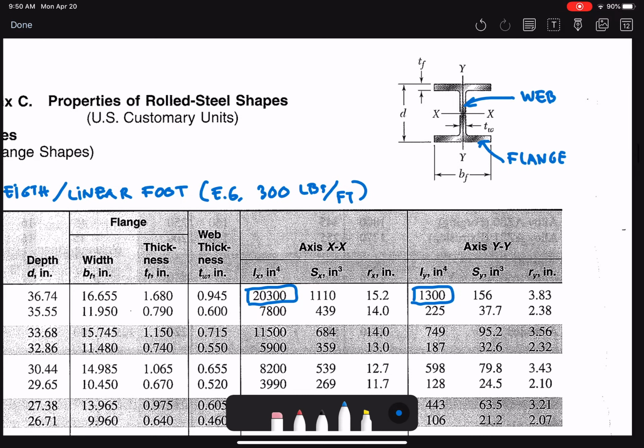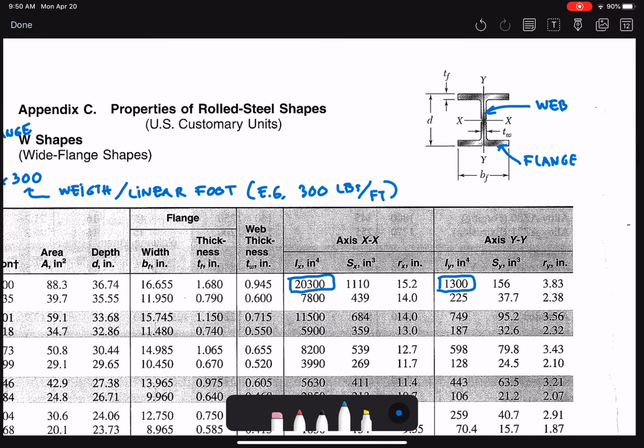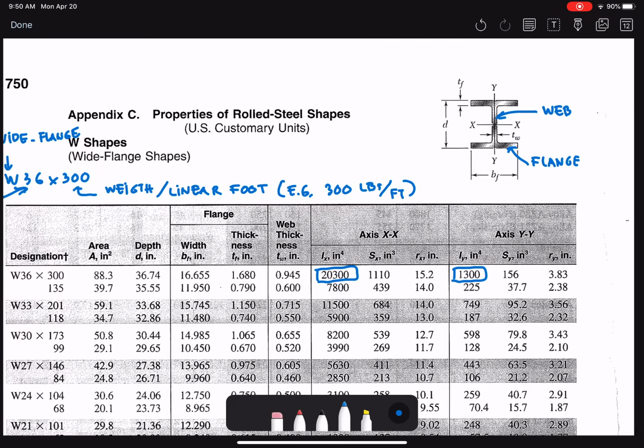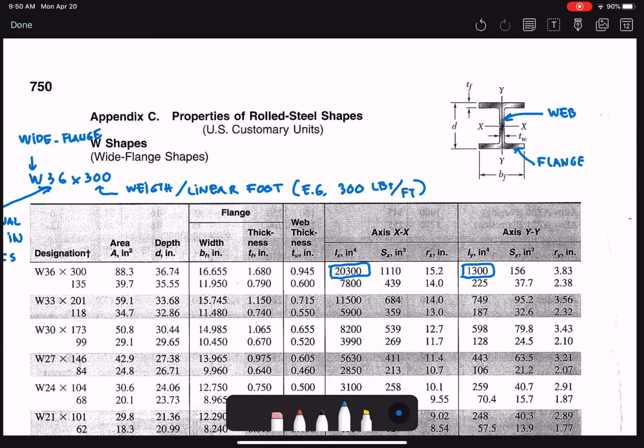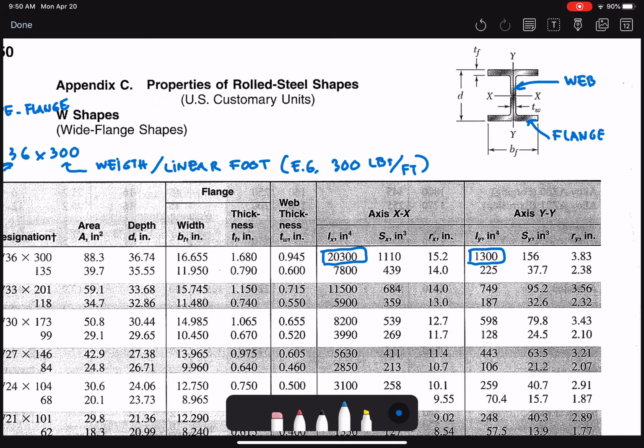If not, you can go back to my demonstration in worksheet 5A, part 1. In that worksheet 5A, you see the demonstration of why it buckles about the weak axis. So when you find the I, we're just looking at Iy, because that's the smallest and it needs to be sustained against buckling. So you select the weakest axis, the one that would buckle.